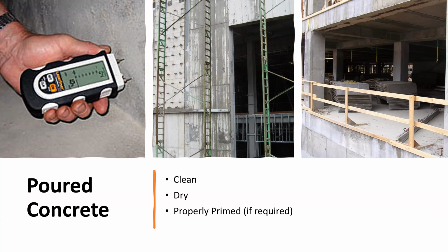Okay, so that's where we're going to want to take advantage of using something that could actually test for moisture content. In the picture here, it's showing a pin probe. Well, that's kind of tough to do on a solid, dense surface such as poured concrete. So there are some moisture meters you can get that work almost like a stethoscope, think of a doctor putting a stethoscope on you and listening to your heartbeat. It's kind of like that, you can actually test for moisture in the substrate.